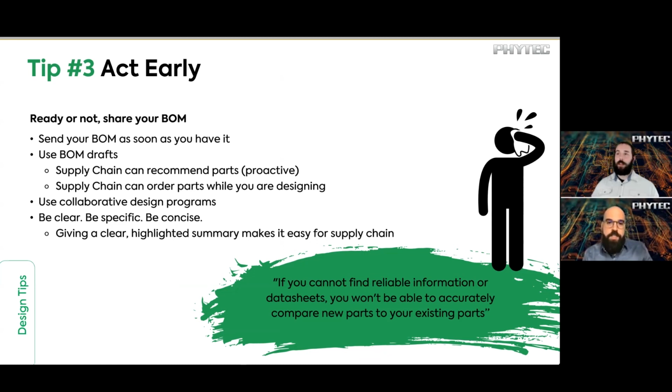And that's a recommendation that if I were to bring that to you when I was specifying, you could come back and say, hey, that's not a current design. You want to switch that out. I mean, there are plenty of other oscillators we could substitute in there that are current designs and would have saved us from the situation. But if I don't present that until the board's fully designed and ordered, there's nothing more we can do.